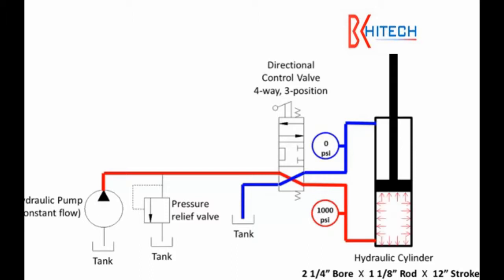If you remember from your high school physics class, pressure acts in all different directions. So there would be 1,000 psi of pressure in all different directions in the bottom of this cylinder. The pressure on the outside walls would try to burst the cylinder open, so we would need to make sure that the wall thickness was sufficient so that the cylinder didn't burst open. The pressure along the bottom would try to blow off the end of this cylinder, so we'd need to make sure that that was strong enough. And the pressure on this piston would try to push the piston up.